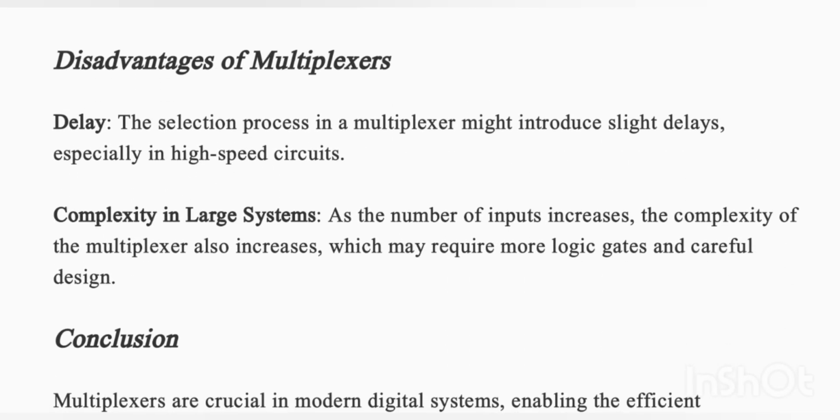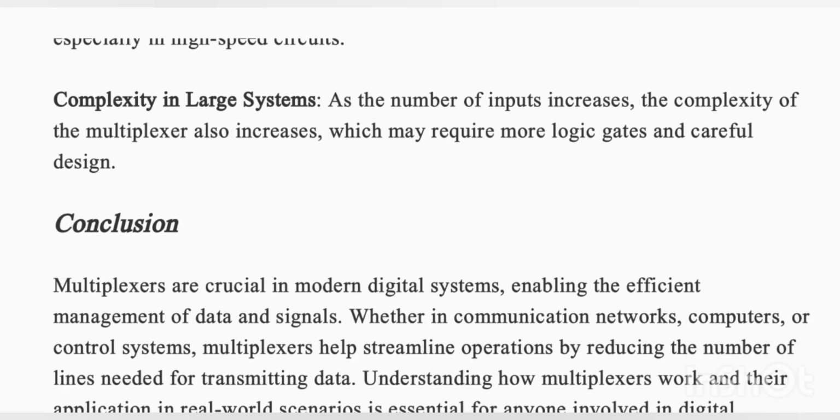Disadvantages of multiplexers. Delay. The selection process in a multiplexer might introduce slight delays, especially in high-speed circuits. Complexity in large systems. As the number of inputs increases, the complexity of the multiplexer also increases, which may require more logic gates and careful design.